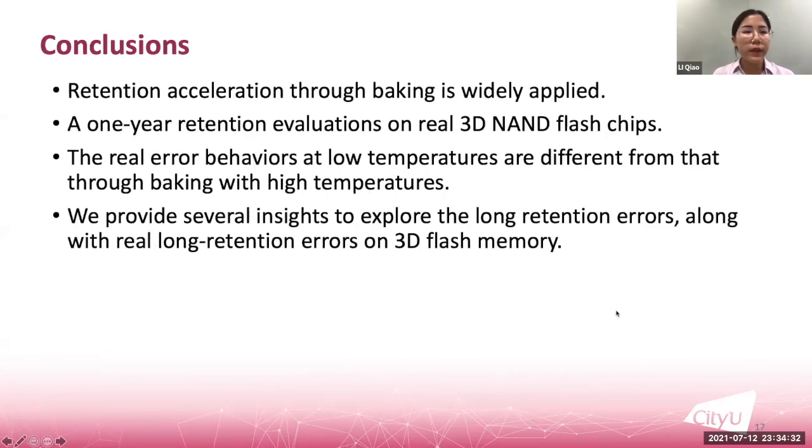Finally, the conclusion of this work. We conducted a 1 year retention evaluation on real 3D NAND flash chips, and we have found that the real error behaviors at low temperatures are very different from those through baking with high temperatures. And we provide the real long retention errors on 3D NAND flash chips.